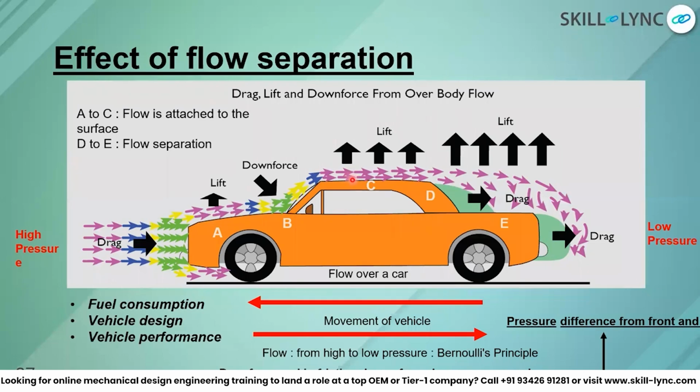If we talk about flow separation in a little more detail, the flow is interacting with the surface of the car at this point where maybe the geometry of the car or the velocity of the car is really high, due to which the separation happens. Separation doesn't happen just because of the pressure gradient. That is one thing by which you can measure it. But of course, the geometry plays a major role in the flow separation phenomenon also. So in this case, we can see we have a curvature, then we have a slant, a 90 degree slant. So the air interacting at these places is not able to fill the space which is behind the car. That's a non-technical way of saying that you have a low pressure over there.